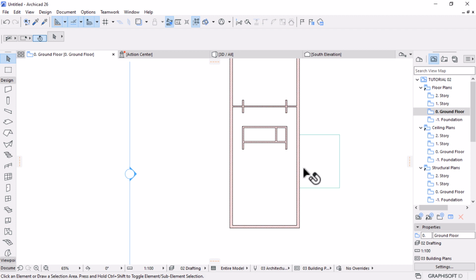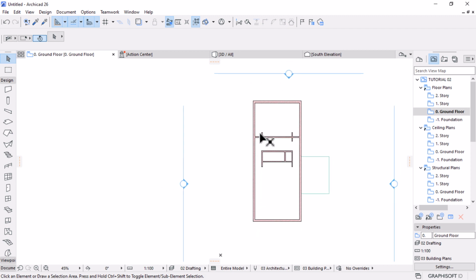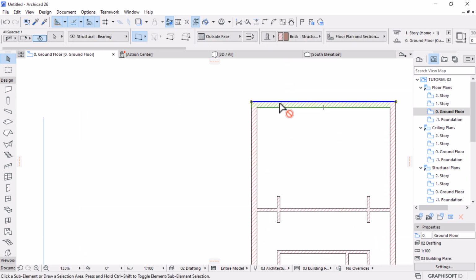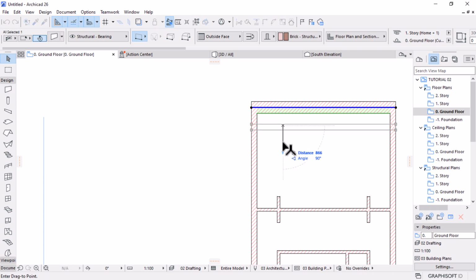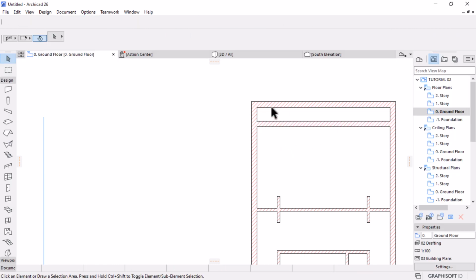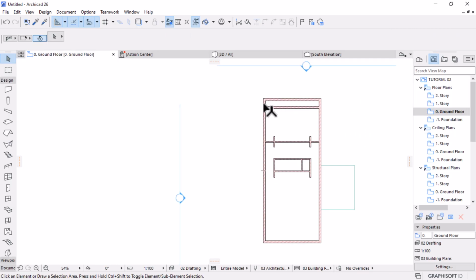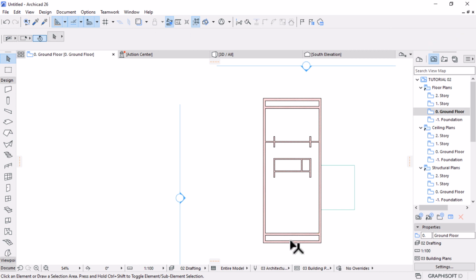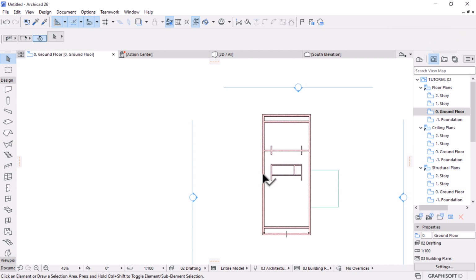We're going to have a sliding door here, and then this side we're going to have full glass coming from that corner around 1 meter. I think, let me just cater for it. I'll pick this wall, Control Shift D to carry a copy, and then move this by 700. That's a meter from where the glass starts, and then I can do the same to the other side like that.